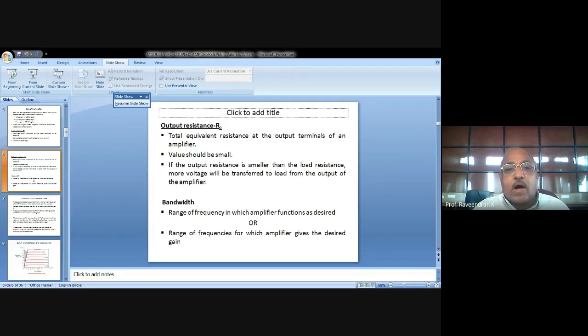There is a 180-degree phase shift between the input voltage and output voltage for a CE configuration. The reason is, for the positive half cycle of the input, when the input increases, the forward bias to the emitter-base junction increases. Why? Because the positive half cycle of the input voltage superimposes on the positive voltage of the DC condition, so VBE will be increased.